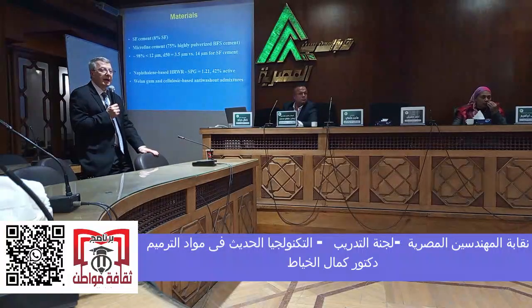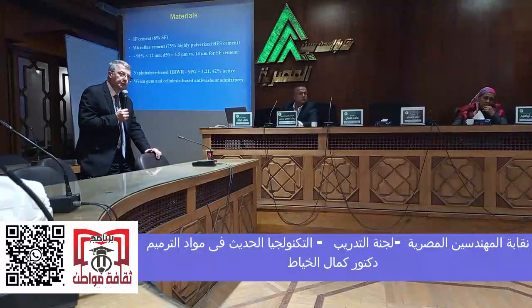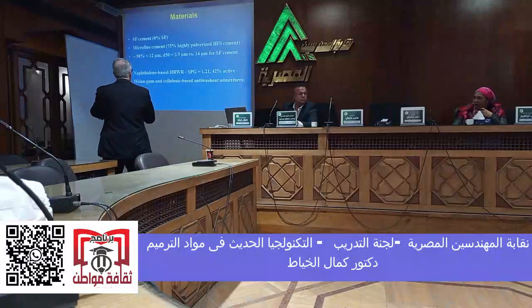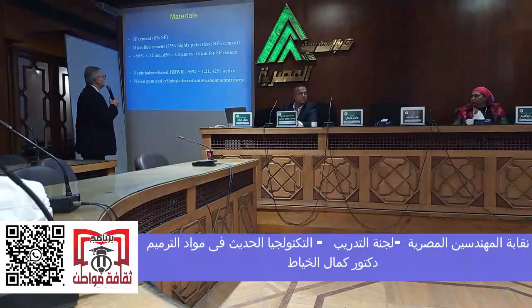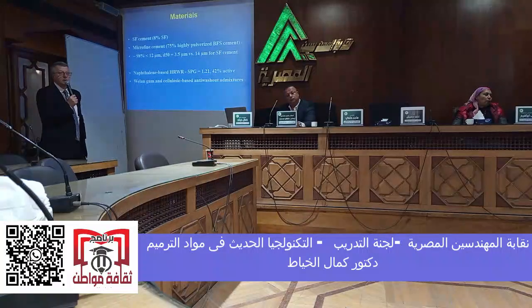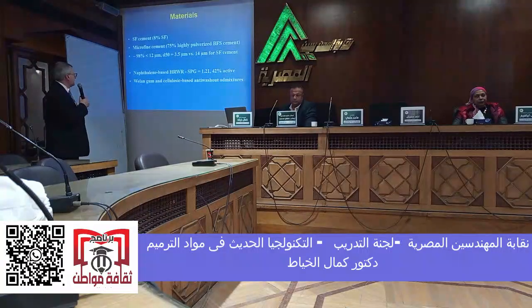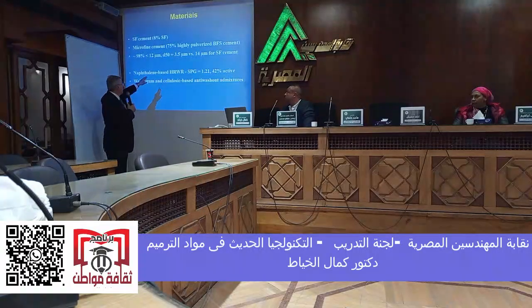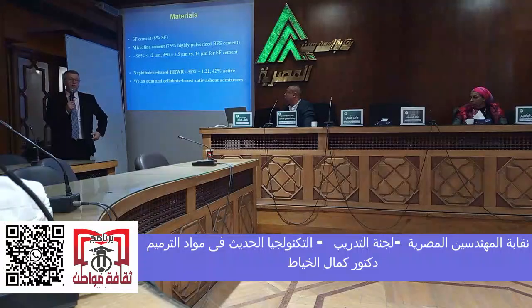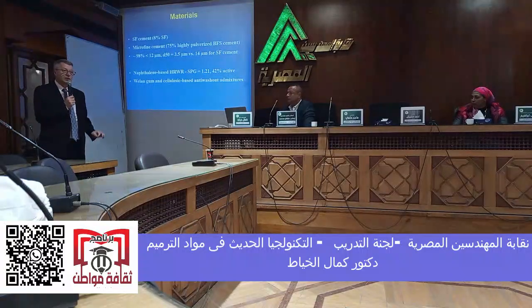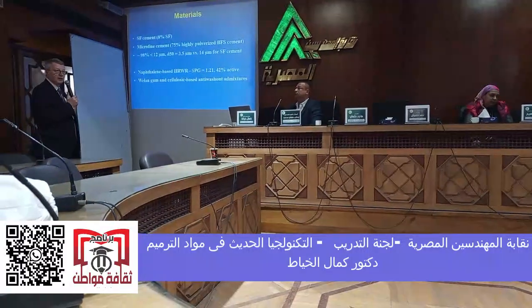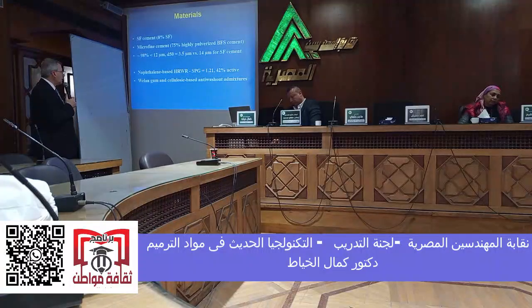I'll show you. We used a microfine cement. We tried Portland cement, type 1 cement, and silica fume. We also tried microfine cement, which is 75% ground GGBS, very, very fine GGBS. You see the D50 is 3.5 micron. The D50 of Portland cement is about 14 micron, so it's much finer and will penetrate smaller cracks. We used naphthalene-based superplasticizer, not polycarboxylate, and welan gum as anti-washout admixture. Next.